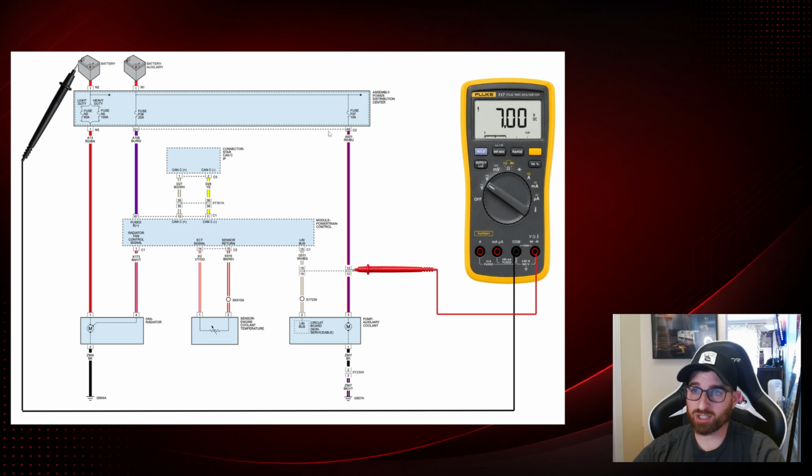But basically with this unplugged, what I did, we had this connector out right here. I pretty much just hooked up a jump box, and I went from this connector to this connector and wired in my headlight bulb, just to load test this wire through this connector to the auxiliary coolant pump. So imagine a probe coming out here and a probe coming out here, and then we ran it through a jump box. It'd be like one lead of the meter, like one lead of a bulb, jump box here, positive, negative, and then we go back to here, and it lit the bulb. So I knew there were no issues along this wire.